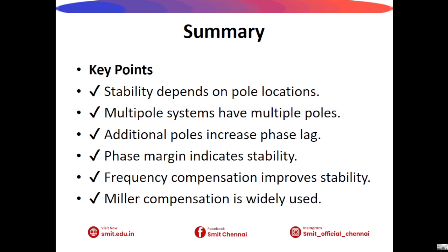Finally, we come to the summary of this lecture. Let us summarize today's lecture. We learned that system stability depends on pole locations. Multipole systems introduce additional phase lag that may cause instability. Phase margin is an important indicator of stability. Frequency compensation techniques such as dominant pole compensation and Miller compensation are widely used to improve amplifier performance and prevent oscillations.